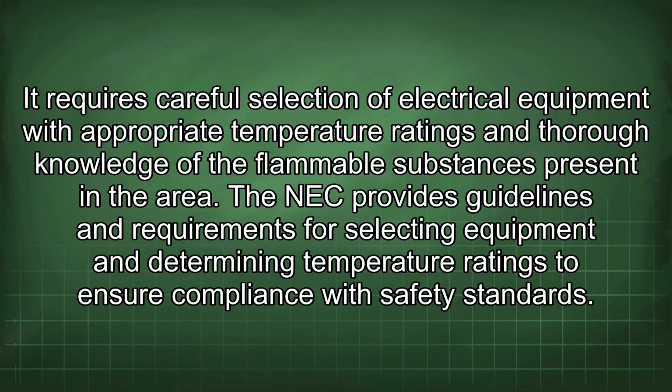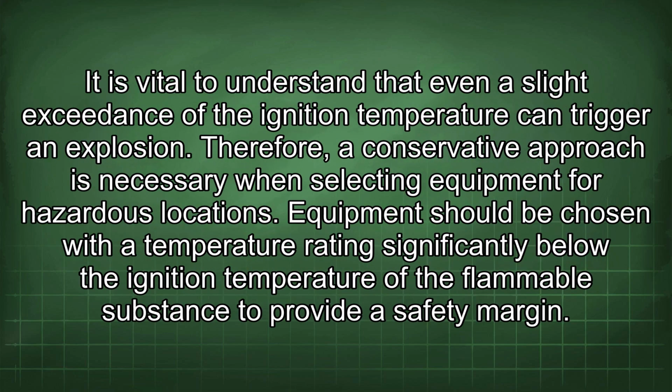It requires careful selection of electrical equipment with appropriate temperature ratings and thorough knowledge of the flammable substances present in the area. The NEC provides guidelines and requirements for selecting equipment and determining temperature ratings to ensure compliance with safety standards. It is vital to understand that even a slight exceedance of the ignition temperature can trigger an explosion. Therefore, a conservative approach is necessary when selecting equipment for hazardous locations. Equipment should be chosen with a temperature rating significantly below the ignition temperature of the flammable substance to provide a safety margin.